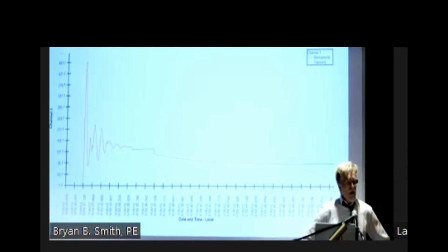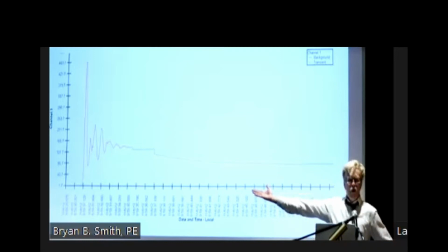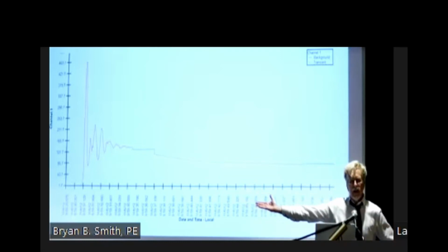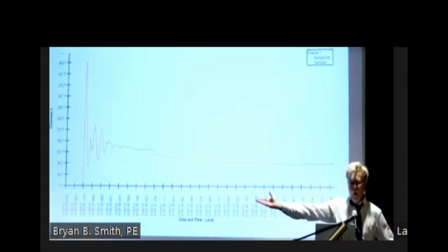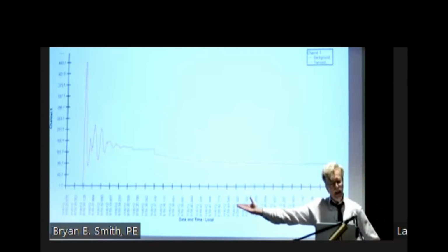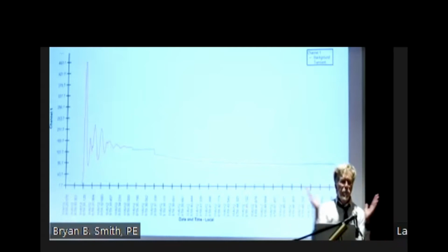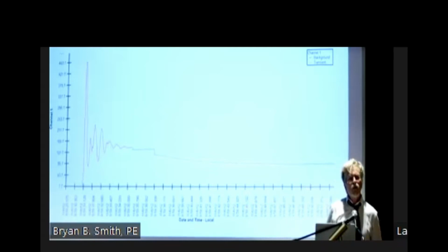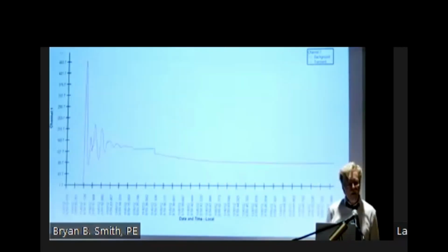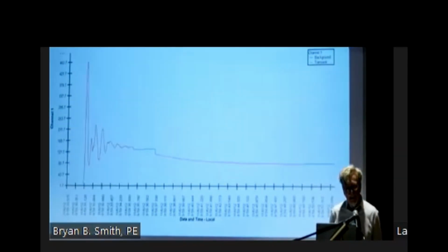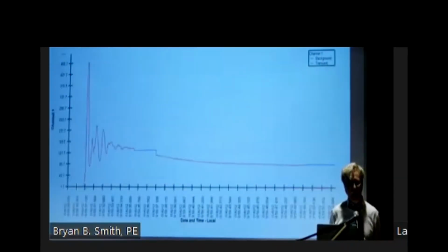I'm just moving air. I'm going way over here to the right-hand side of my curve. I have no resistance. This is good. I'm spinning fast. This is crazy. And then all of a sudden, bam, I start pumping water. Guess what happened? My system that's designed for 90 PSI just got hit by 463 PSI when I started up that pump.